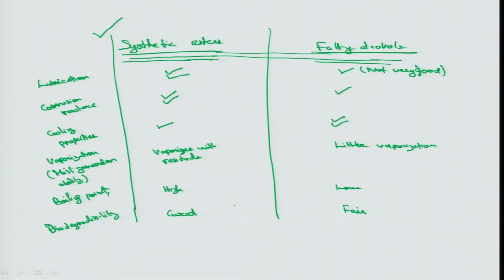There are certain application areas where dry machining and minimum quantity lubrication can be used. It involves a wide range of material processes and combinations of these, maybe drilling, reaming, turning, gear cutting, and various materials on which these kinds of machining can be applied, for example aluminum alloys, steels, and titanium. Near dry machining can be used on titanium, but dry machining cannot be done on titanium alloys, because titanium does not have very good heat dissipation properties.